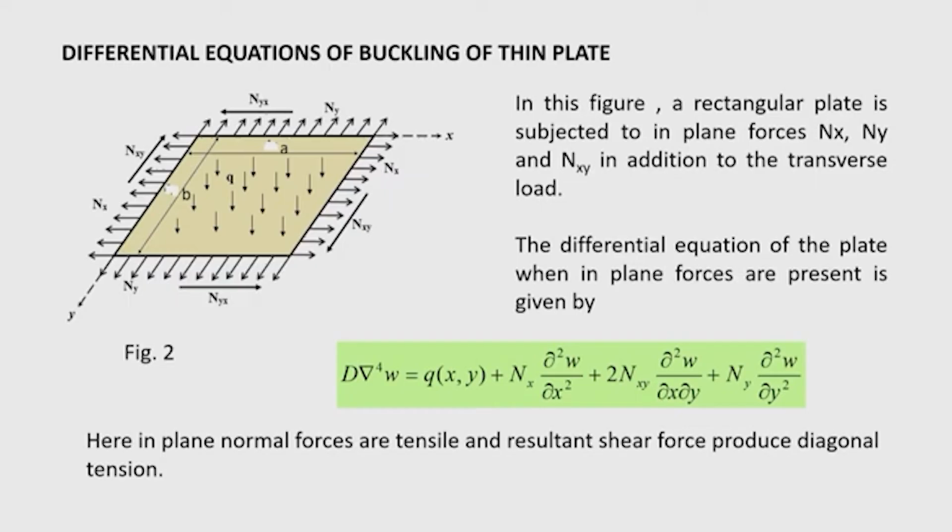Now, if I consider the action of in-plane load as a fictitious load on the plate, then we write the equation of the plate subjected to simultaneous bending and stretching, that is the simultaneous action of this transverse load and in-plane forces.